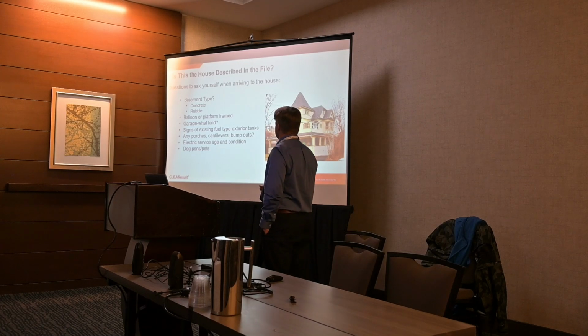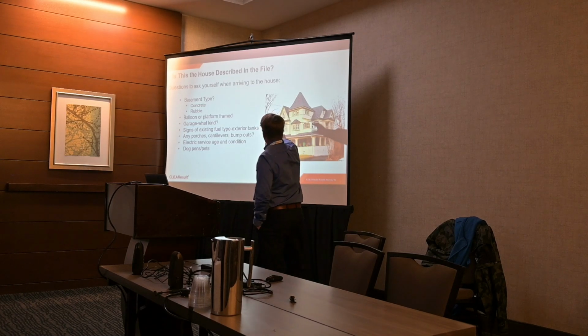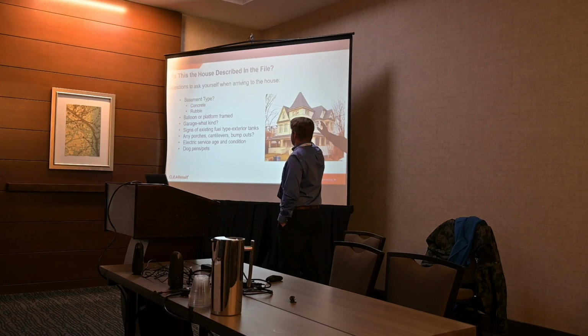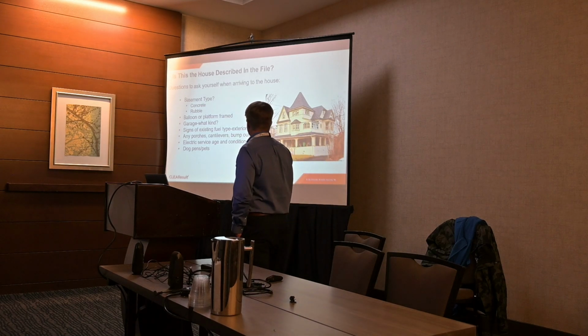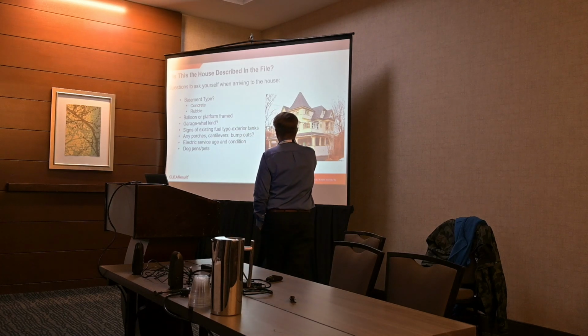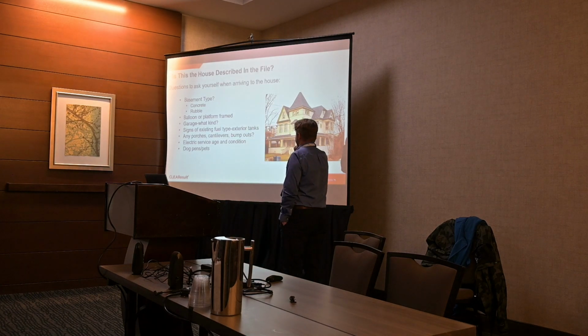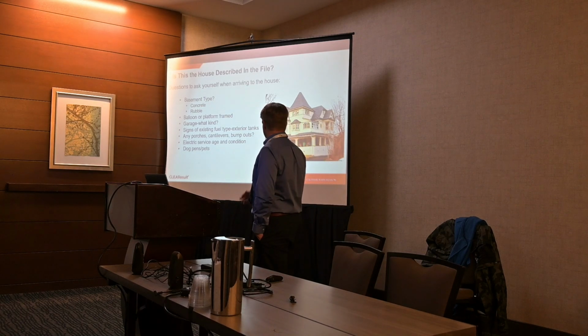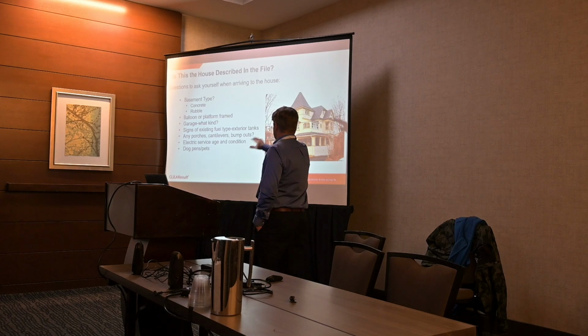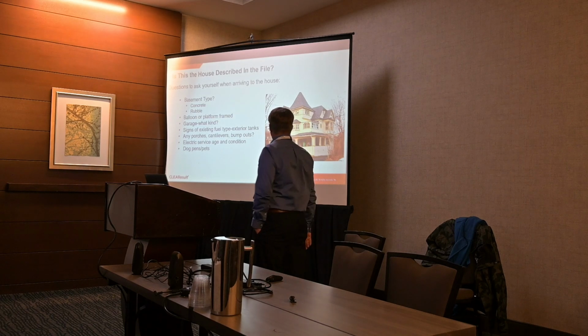Doing air sealing that's not actually going to save money. Existing fuel types. The intake says that it's oil, and you pull up and there's a gas meter, right? So verify the fuel types. And then, different types of house features that make the house more difficult to make tight. Porch roofs tying in, cantilevers, bump outs, all these sorts of things, especially in these older homes. You never know how they're framed and how you're going to get those things tightened up. And then again, electric service, and then dogs and things like that.